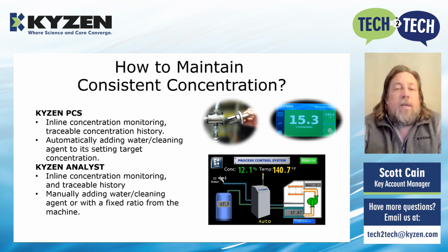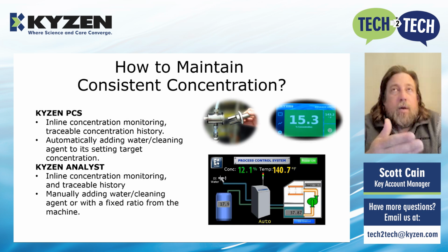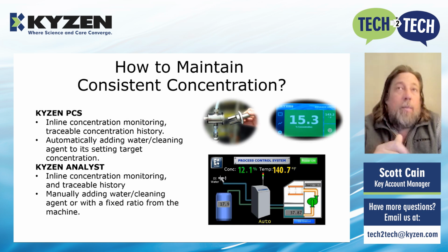What are the ways we can maintain that consistent concentration? So we can use the sonic velocity that we talked about, and KYZEN has two products that utilize that. One would be the KYZEN PCS. KYZEN PCS is an all-inclusive machine. What will happen is it will document what the concentration is. It uses the sonic velocity to determine what the concentration is. And then if it needs to add water or chemistries to stay within that range, it's going to do that automatically. There's no manual testing on it.